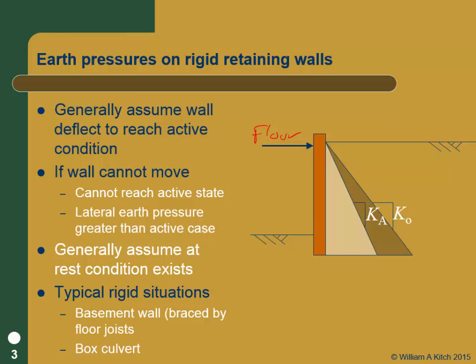All right, that's a rigid structure, and you need to design for earth pressures that are rigid. Now, in addition to having this problem, if you start going back there and compacting, you're going to see in a minute that if we have flexible walls, once we compact, the wall just moves more, and we may increase the earth pressure some, but there's a limit to what we can increase them to.